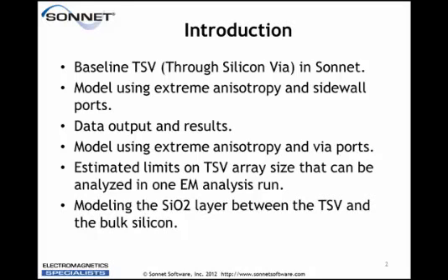After we demonstrate the via ports, we will estimate what the limits are on the maximum size of through-silicon via arrays that can be analyzed in a single EM analysis run. And we'll also show how to model the silicon oxide layer between the through-silicon via and bulk silicon. It insulates the through-silicon vias from the bulk silicon, and this is easily modeled by modifying the dielectric properties.